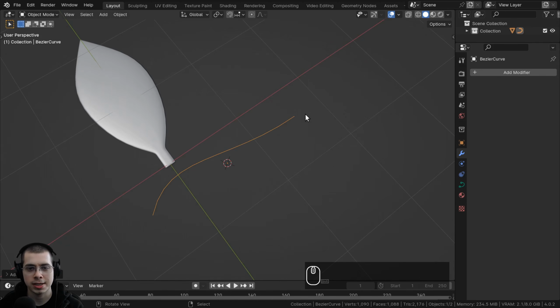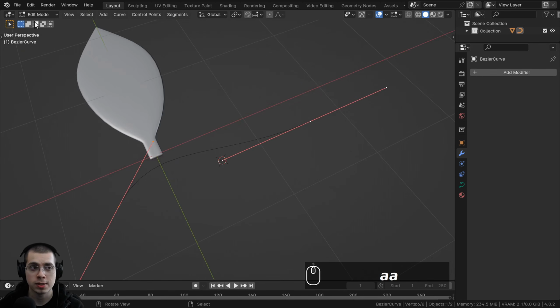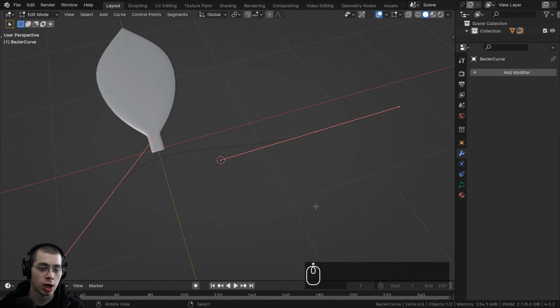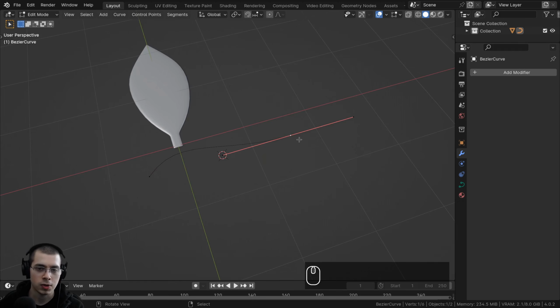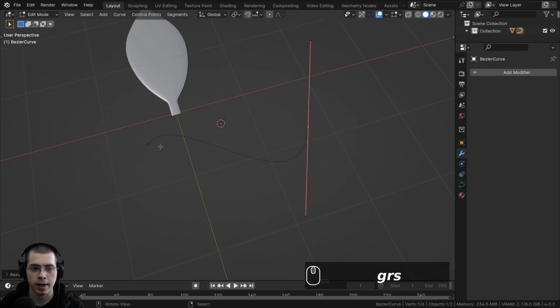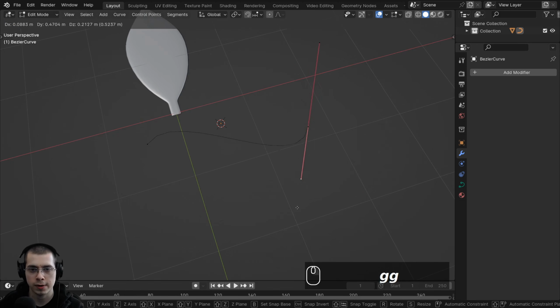So when I add it, you can see it is just a little line here, and it is nice and smooth. So you can go into edit mode of the curves. You can see here we are in edit mode. However, when we go into edit mode, we can't actually edit the geometry. So there aren't vertices and edges and faces. There are instead these curve handles. So if you select the curve handle, you can hit G to grab, R to rotate, and S to scale, and you can scale the curve handle. And you can see the curve object is going to rotate by the handle. And you can also select the end of the curve handles and kind of rotate this or kind of bring this in if you want to have it curve really sharply or curve much more smoothly. And then there's that on the other side as well.